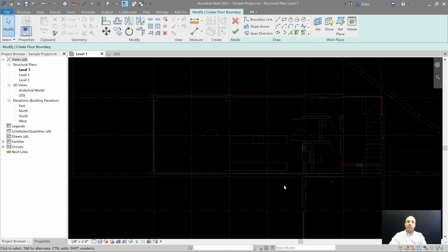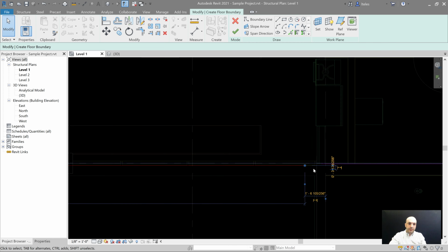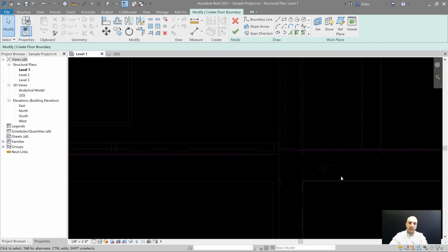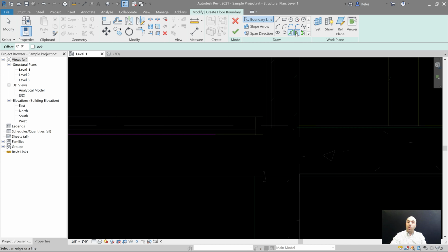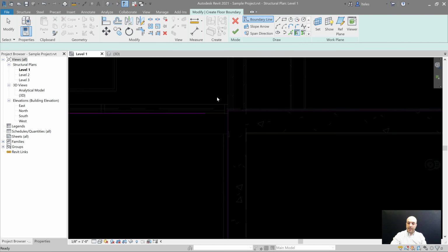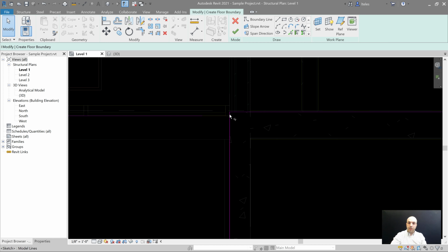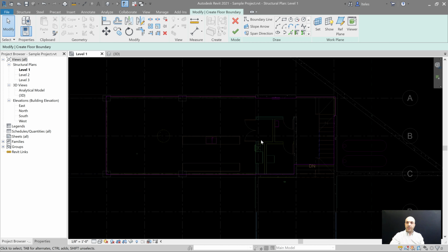All right, so we are almost done with our loop, but we have to make sure that this line is going to line up with that line. You see, because we have a wall on one side, but we have windows on the other. So we need to draw a line here to represent this notch. So let me go pick lines. You can also use pick walls here to pick the outside of that wall like that. Okay, that's also an option. And then I'll use my trim command, TR, to trim this together. All right, so we got the edges of our floors.